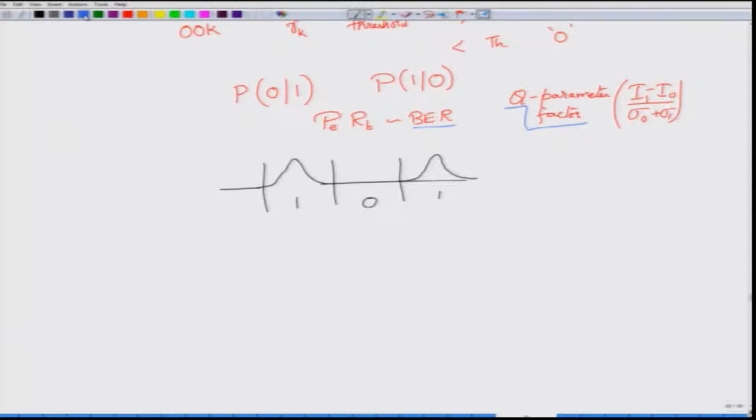When the chromatic dispersion is very large, then what happens is that the signal would almost be flat, in the sense that it would be spread out quite a bit, and then in the slot of 0 you might actually see something like this. So, this would be the situation when the chromatic dispersion is very large. However, this does not enter into the BER or the Q factor, not at least until you make some additional modifications to the expressions for BER or the Q factor.